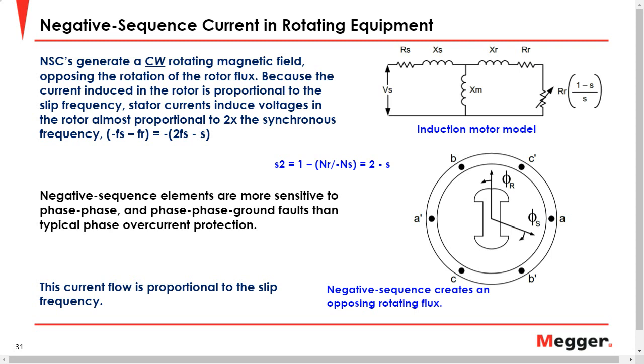So what I'm trying to say is, in the other case, the full voltage was producing a current that was, well, not very small, because the currents tend to be relatively large: the voltage induced on the rotor divided by the very small resistance in the rotor gives you enough current to produce torque.